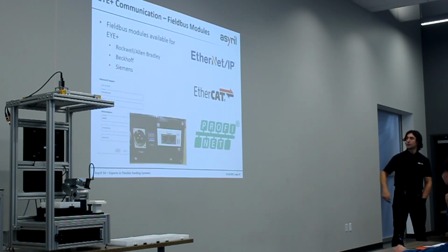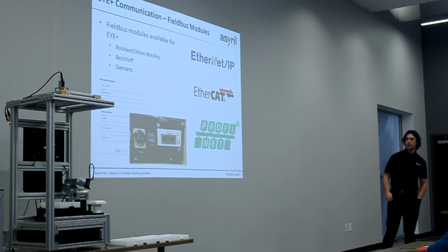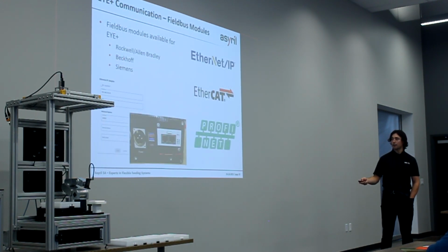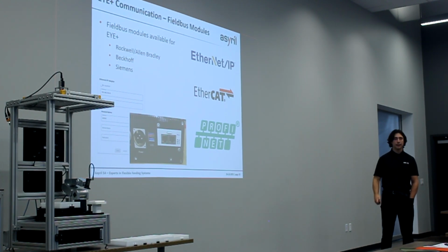If the queue is empty, it's going to know that the queue is empty and say, hey, it told me to prepare a part, my queue is empty, the robot's away, I'm going to vibrate the platform, collect another image so that when the robot's ready to come pick again, I have another part in my queue, so I'm ready to go. We also have some more advanced commands in our documentation for scenario specific application questions, I guess.